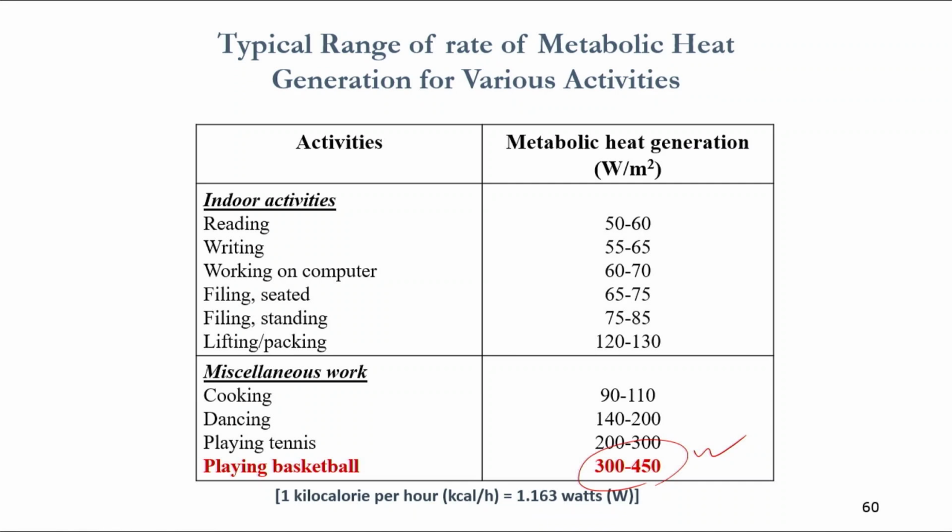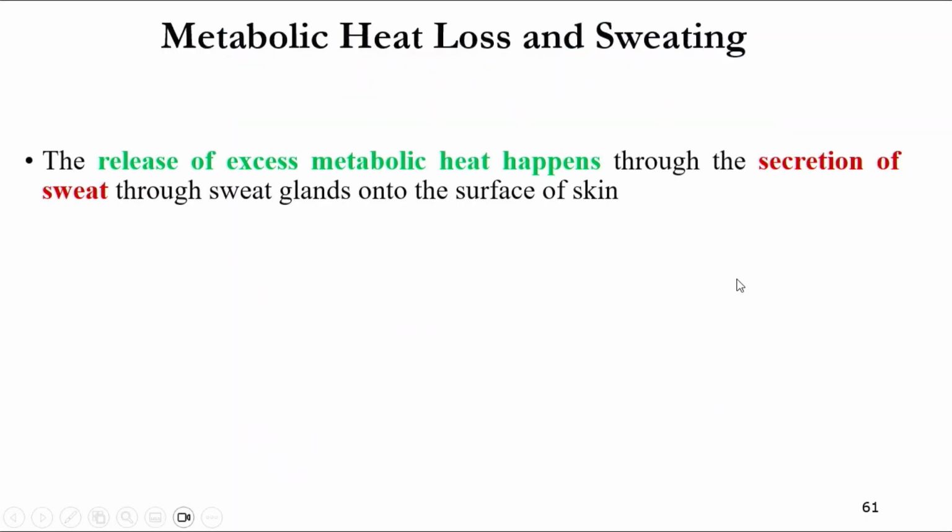Like a worker working in front of, say, a furnace. Here all the heat we are receiving, and body heat is also generated. In that case, through dry heat transmission we cannot keep ourselves comfortable. There the evaporative heat release has to be there. So, this is a very complex scenario.